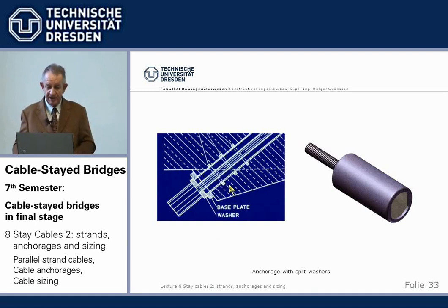They have an inner opening which goes just around the cable, and they are wide enough to bridge the distance between the anchor head diameter and the inside of the steel pipe. So they are placed here and they are resting on a base plate, and you can calculate all that. But that's what basically prevents the anchor heads from slipping through where they came from.